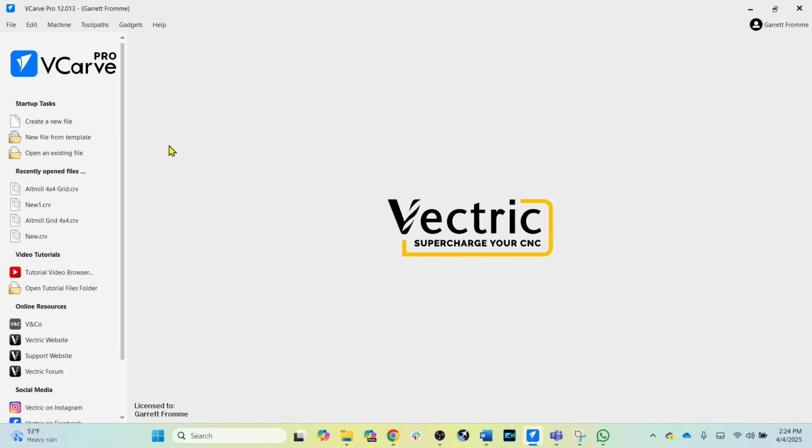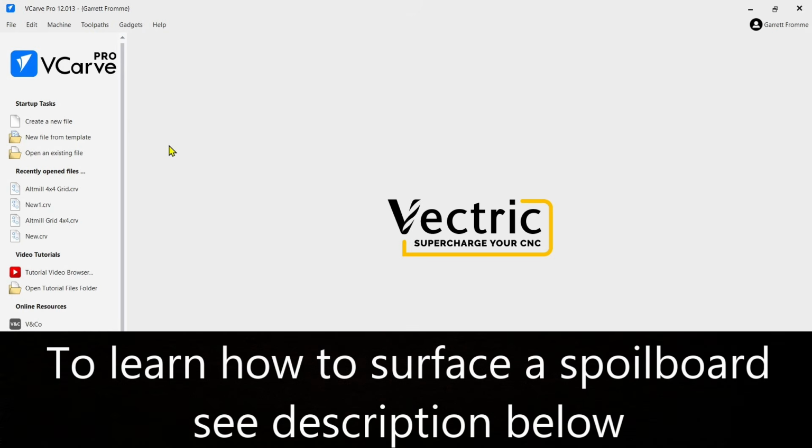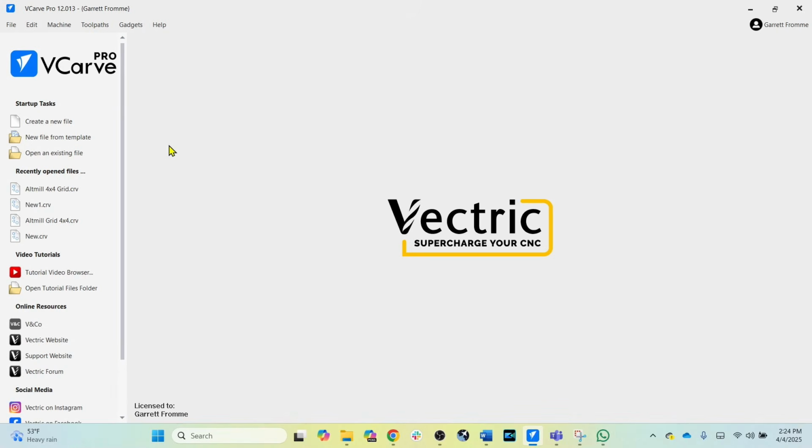A quick note before we begin. You need to have your spoil board surfaced before you actually start cutting the grids on your machine, because you want the spoil board to be flat. So if you haven't surfaced your spoil board and you want to know how to do it, I've got a video and I will link that down below in the description of this video.